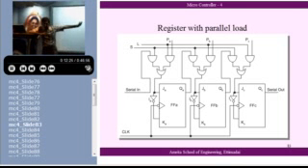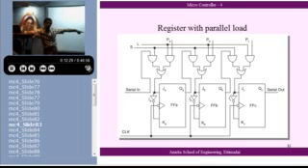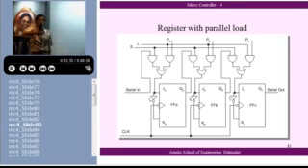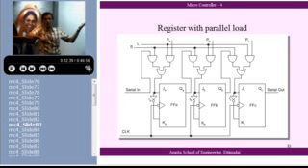Okay. Serial output will come. If you ask what is going into the first flip-flop, that will be decided by the serial data input here. Clarify the point. Okay. So I can do parallel loading, I can do serial output. By combining that, I can have serial input, serial output, parallel output.